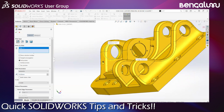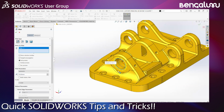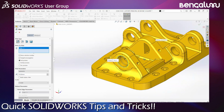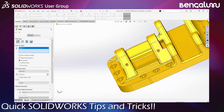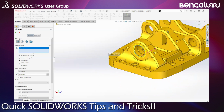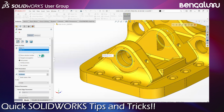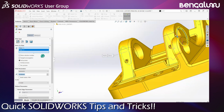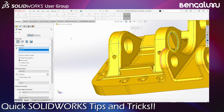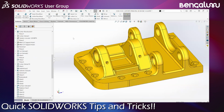But actually, when you select the fillet operation, you need not even rotate the model. You can see that you can select through the faces. If this is the edge where you want to add the next fillet, I can keep the model as it is, and even without rotating it, I can get to that particular edge. This is basically because the fillet lets you select through faces, and it saves you a lot of time. You need not rotate the model each time to select the edge where you want to apply the fillet, right?